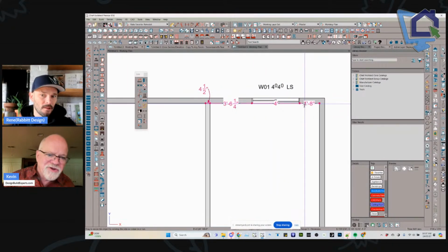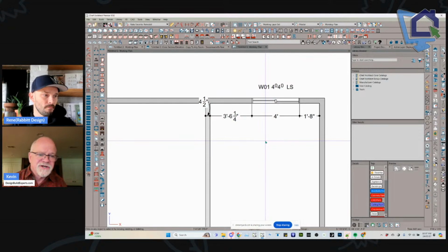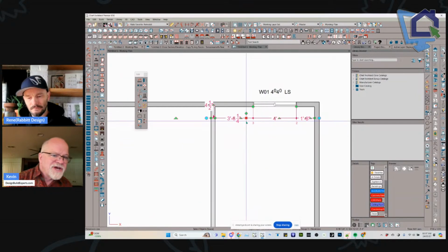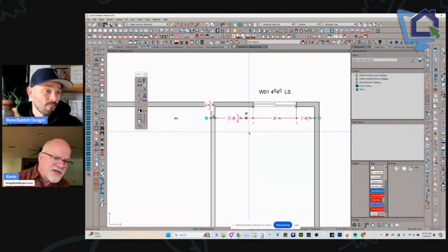So if you're avoiding interior dimensions or auto interior dimensions because of the clutter, setting the reach is a really great way to avoid the clutter and get only the primary dimensions. In your case, you've got it set up so small that you pretty much have to be on the window in order to pick it up, right?